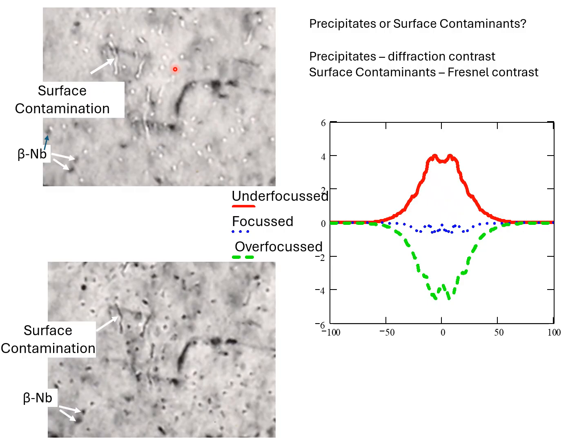So if you have a sample and you say, oh, I don't expect to see a cavity, and there is this thing that looks like a cavity, check it out, do some stereomicroscopy, and verify for yourself that this is within the foil and not on the surface. So I've used this effect to some value in the past, during my studies on zirconium pressure tubing.